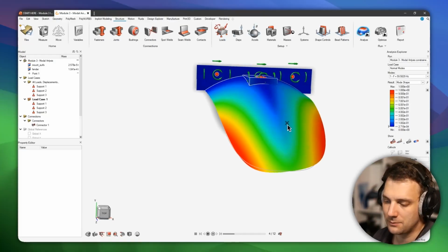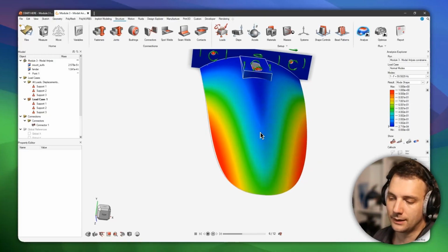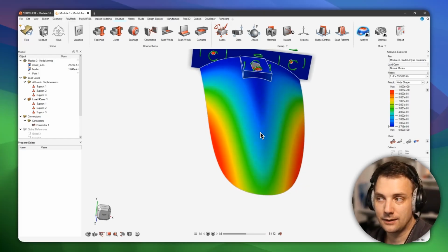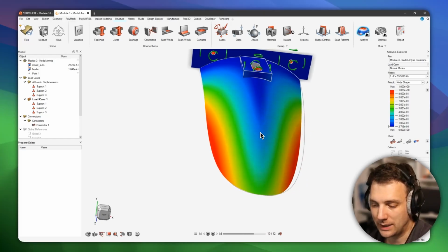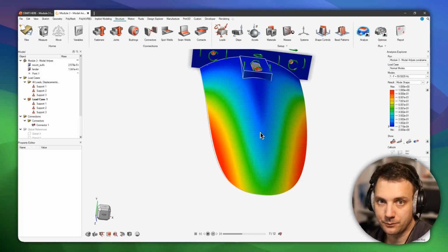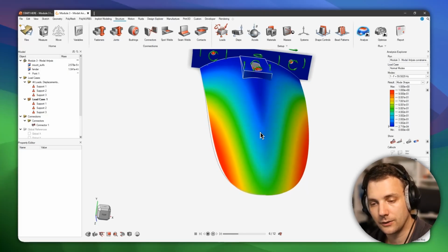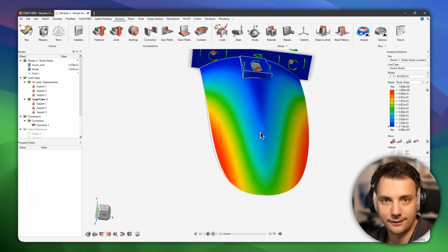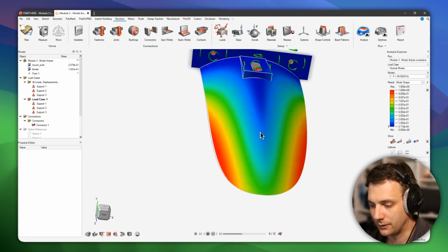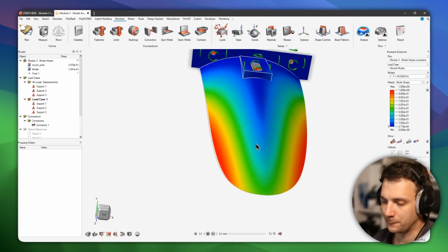And you could imagine that this would be somewhat of a weak mode of this part. Weak, I mean a low frequency, because the more stiffness you have, the higher the frequency it would be. Just imagine the strings on a guitar. If you have the low E note, it's a lot less tense than the high E note, for example, right? So stiffness and frequency are related.